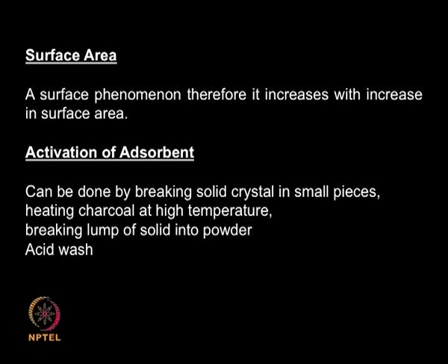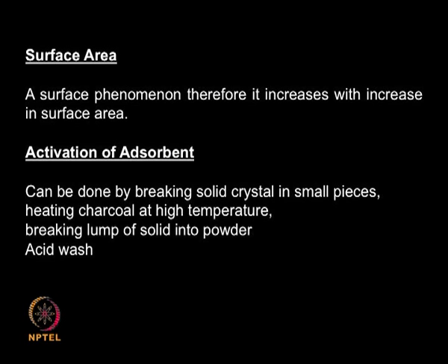Next one is surface area. Because adsorption is a surface phenomenon, the more surface you have, the more interaction between the two phases, so the adsorption process also becomes very effective. So having a very large surface area is the key to any adsorption process. That is why you have activated carbon sold in the market having several hundred square meters per gram as its surface area. Creating high surface area carbon for adsorption is a big challenge, and that is what industries do actually. So surface area is a very important parameter, and all the adsorption materials used here are high surface area materials.